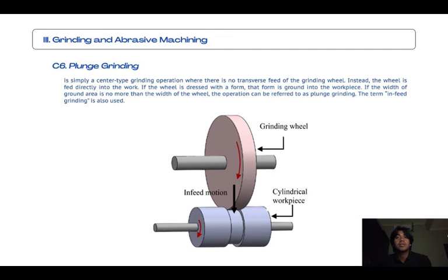Okay, next is abrasive jet machining. It provides cutting action from the effect of finely powdered abrasive in a high velocity stream of gas. Masks of rubber, glass, or copper may be used to help limit the abrasive action. The process can be used for drilling, cutting, etching, trimming, cleaning, and deburring operations on a variety of metals and non-metals, especially hard and fragile materials.